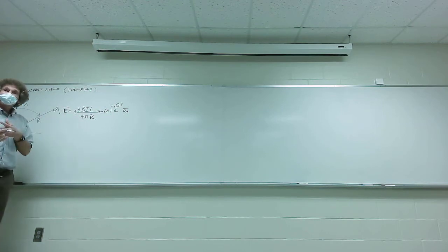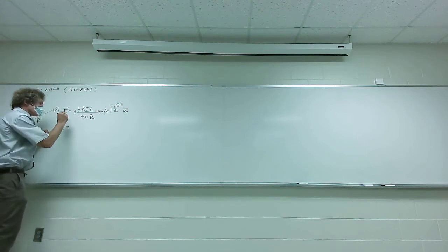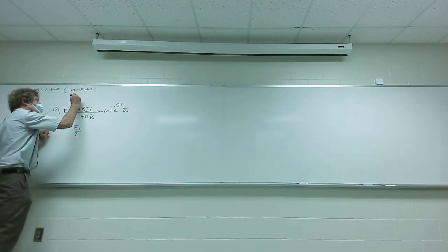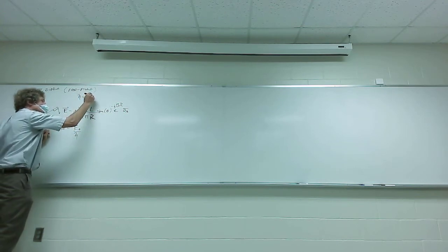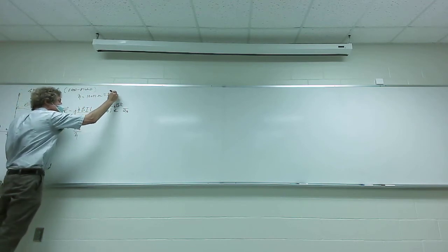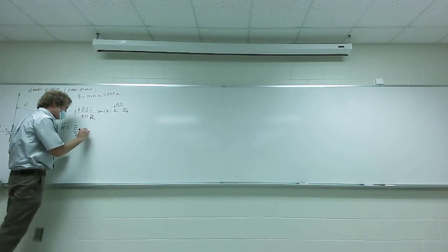The j term means the phase is 90 degrees, but that's kind of an abstract concept. This is a steady frequency. That doesn't mean much. Y'all follow me on this? All right, now if we want the H field, since we're in the far field, we just take E in the theta direction and divide it by eta. And eta is 120 pi ohms, or about 377 ohms. It's just that of free space, the ratio of E to H. And it would be in the A phi direction.